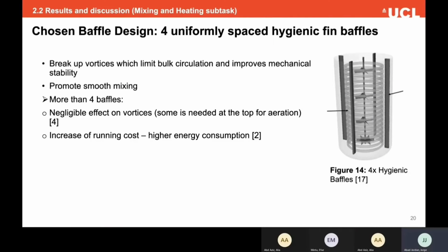Baffles reduce the tangential component of velocity and effective heat transfer coefficient, thus reducing the chances of vortex forming, increasing fluid velocity, reducing mixing time, and creating a better heat distribution. However, having more than 4 exponentially increases the energy consumption due to lower pumping efficiency.